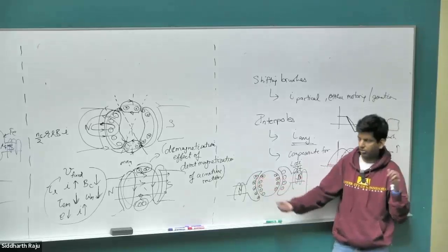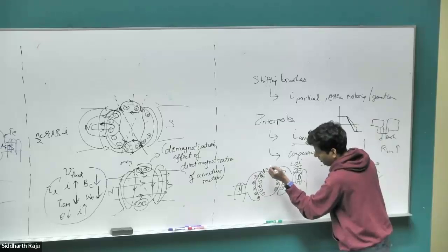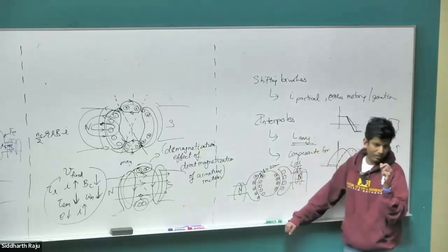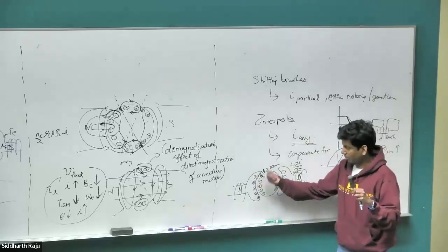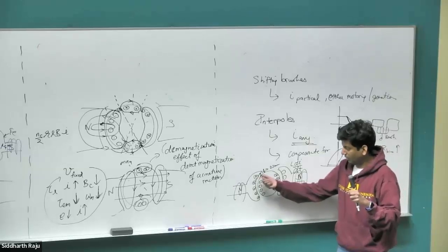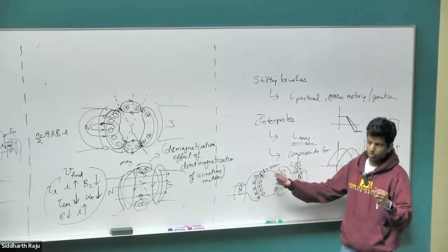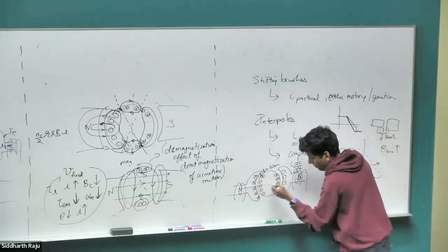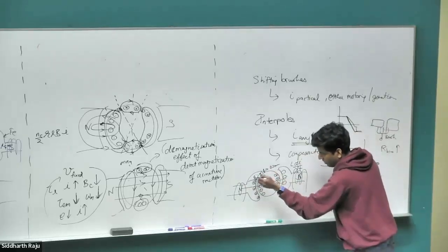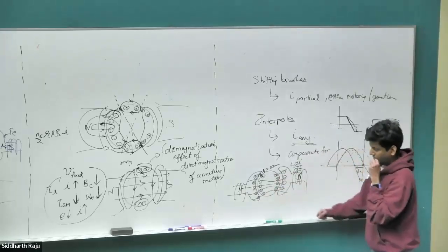Right? They are in very close proximity. Here I've drawn it in an exaggerated manner, but the air gap is very close to zero. It's like 0.2 millimeter or so. So it's a very tiny distance, especially in large motors. So whatever B field this conductor is creating is going to be exactly cancelled out by this B field. So the only B field that remains is whatever is due to the magnets. Right? The rest of the B fields are fully cancelled out by the compensation winding.